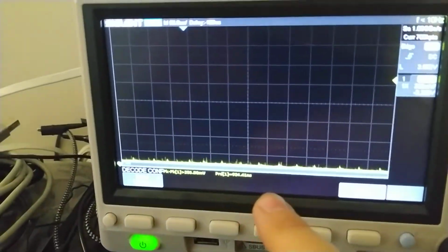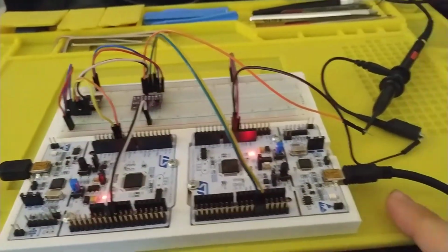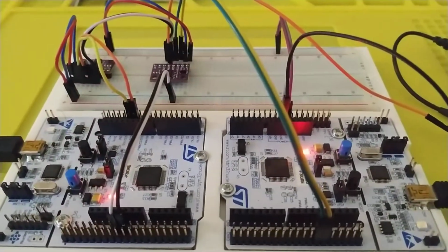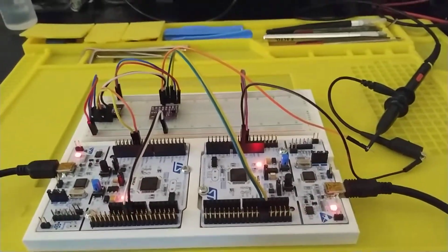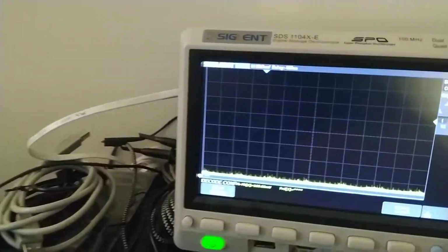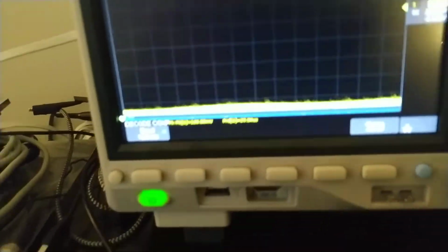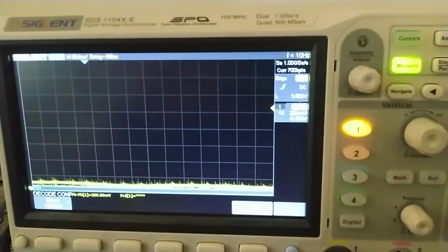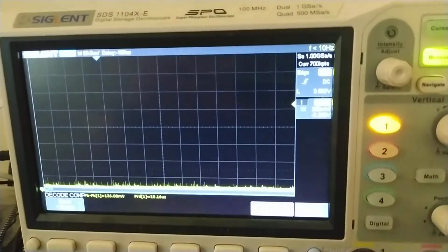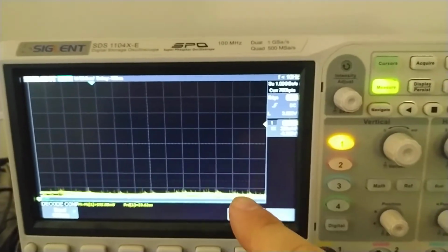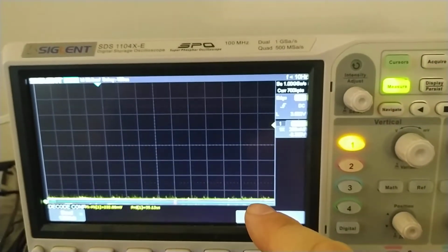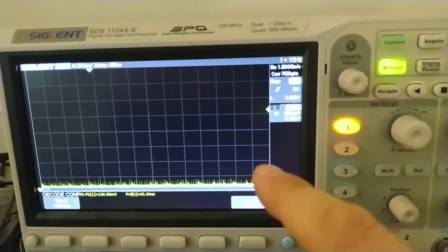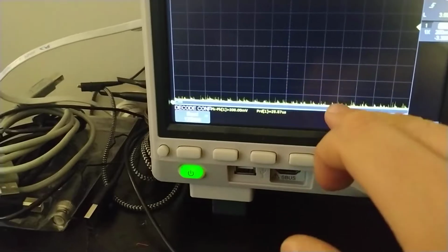One thing: the power supply I'm using here I just connected to the wall, and it's kind of noisy. If you connect to the USB ports of a laptop, for example, the signal will be a lot cleaner. You can see the noise on the floor, but we're going to leave it like this just for this example. So we know we're at about 3.2, 3.3 volts, and CAN high is going to be above that, so we need to drop our vertical position by 3.3 volts.